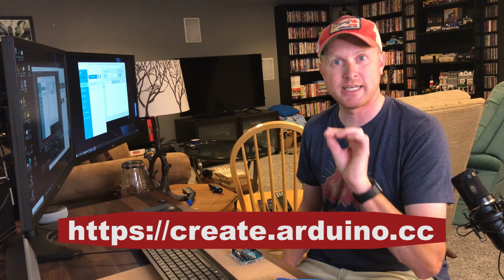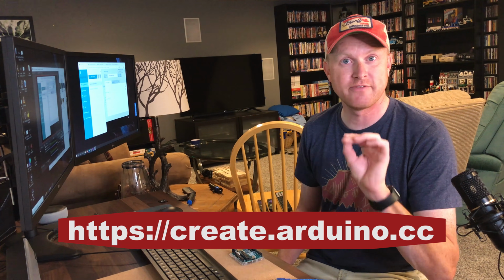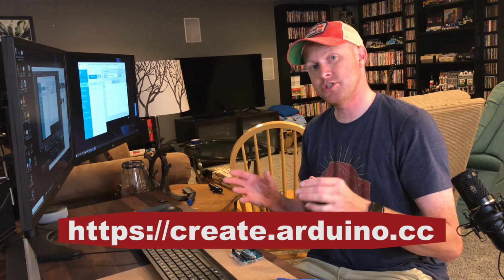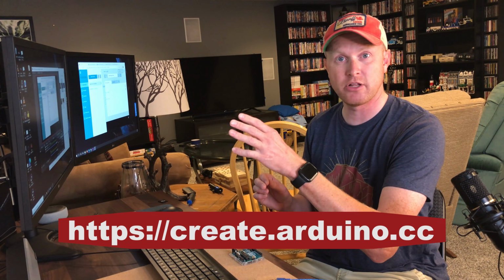Now, for setting up our software, the first thing we're going to set up is the software for our Arduino. Like I said, you can use an authentic Arduino, or like me, I'm going to be using a generic clone of an Arduino. There is a little bit of difference between these two devices because they each use a different device driver to be able to program them. So the first thing we're going to do is go over to create.arduino.cc and create an account if you do not already have one. This will allow us to use their web editor to install our program online and then transfer it over to the Arduino using a USB cable.